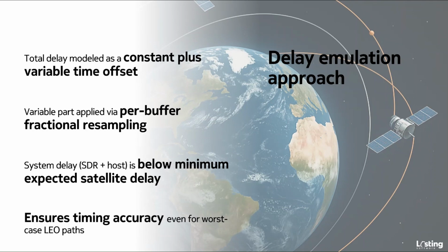The supported delay ranges from 2 milliseconds to 1,000 milliseconds, which is supporting LEO, MEO, GEO, and beyond, and down to 1.5 milliseconds for lower bandwidths, but this applies to bandwidths below 40 megahertz.